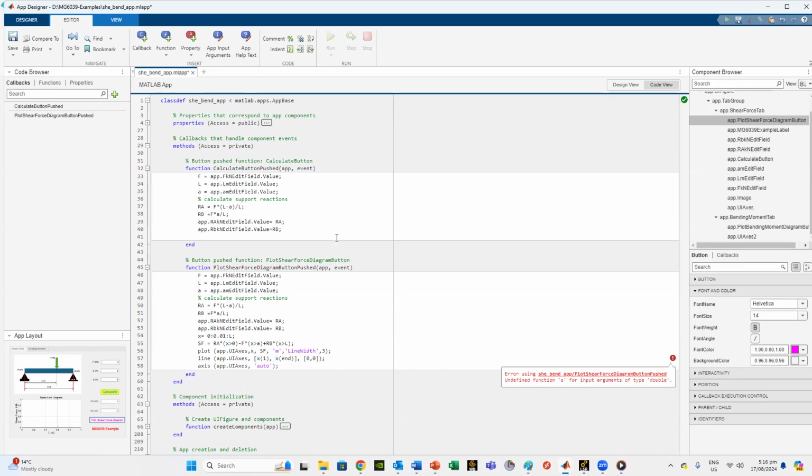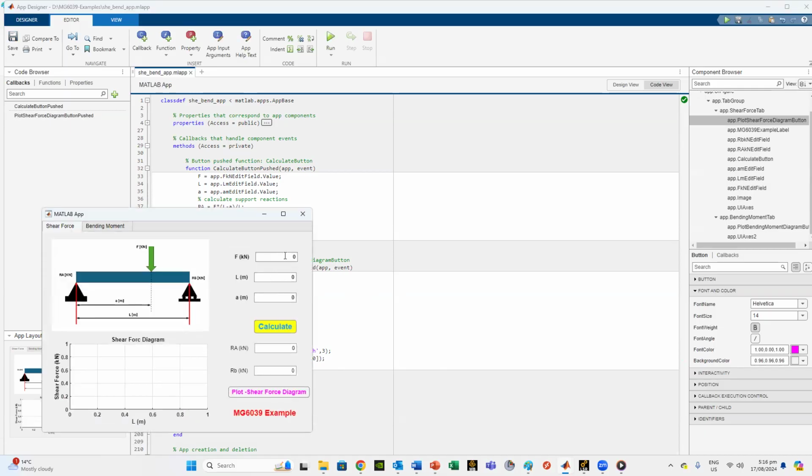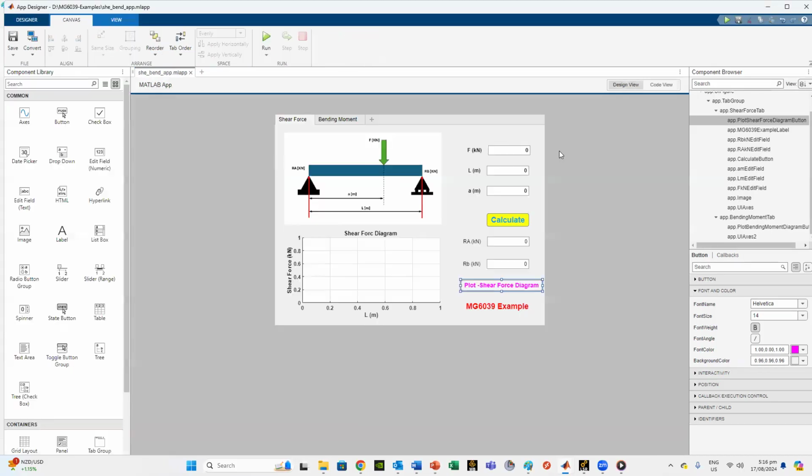It's picking up all the errors, and it can tell me what I missed. Again, 10, 6, 3, calculate, and then plot. And that's what I'm trying to show you. So it's successfully plotted for me. It's going up by support reaction 5, and then the point load is pushing in the middle, 3 to 10, which is negative, from 5 to -5, and then goes here, and that will go up to that value. Awesome. So that works with no issues for the app.